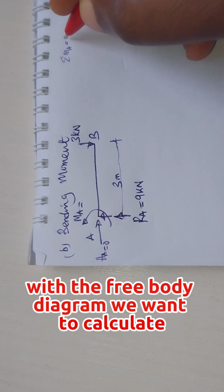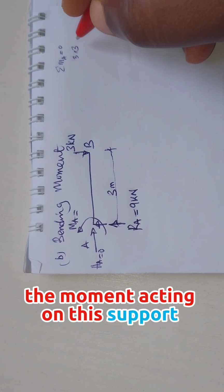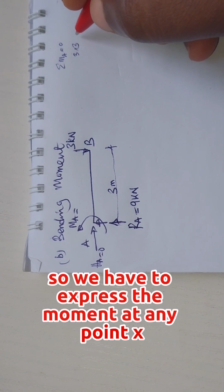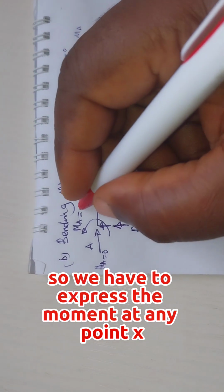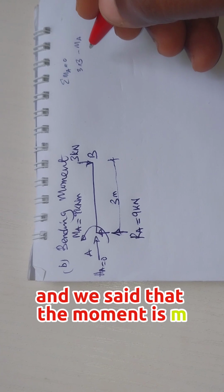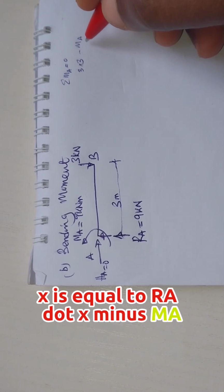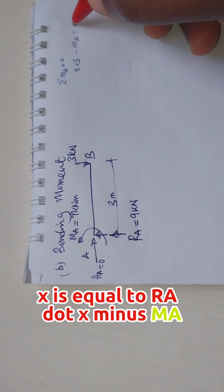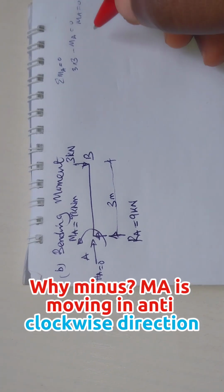With the free body diagram, we want to calculate the moment acting on this support. So we have to express the moment at any point x along the x-axis on this beam, and we say that the moment M(x) is equal to RA times x minus MA. Why minus MA? Because it is moving in the anti-clockwise direction.